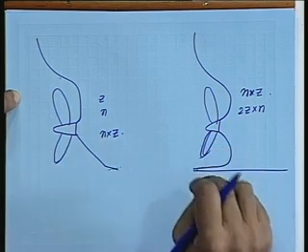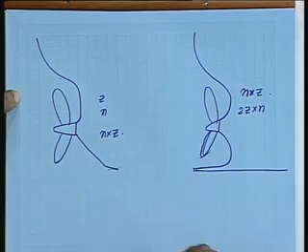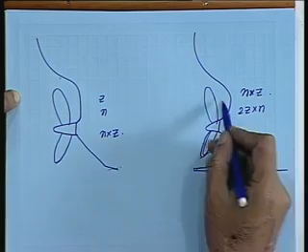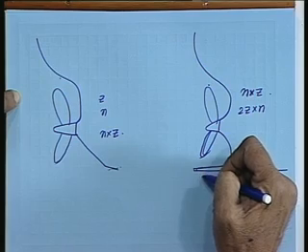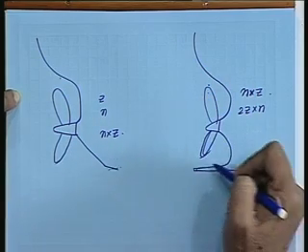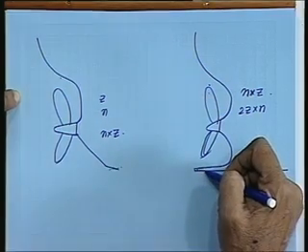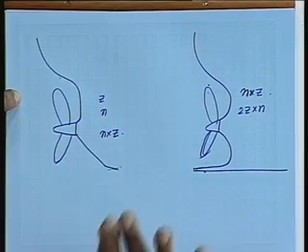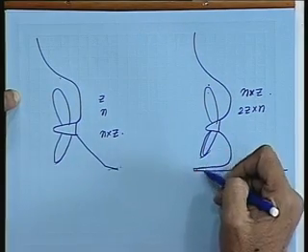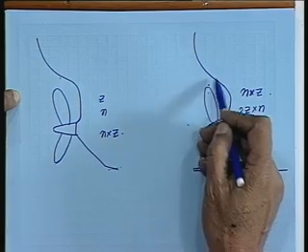Suppose let us take an example that in a tugboat you are having, say, a 3-bladed propeller. So if one blade is coming here, the next blade is not coming here. After this blade moves out from here, the next blade goes closer to this and generates some sort of a frequency here. When it moves out, the third blade goes past this.